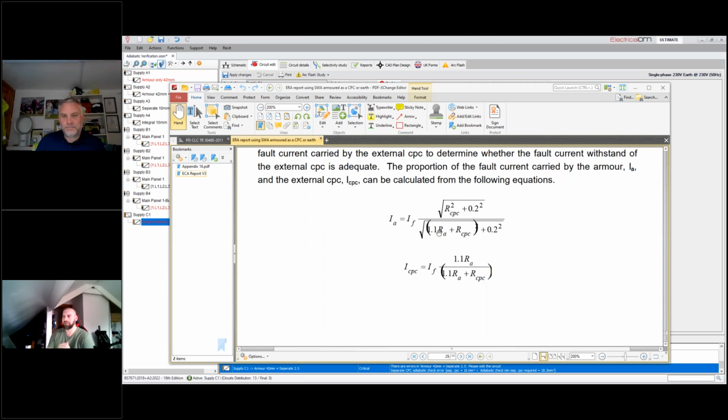Generally, it will be bonded at one end or somewhere naturally for your touch voltages and the like. Generally, it's always bonded for EMC purposes, for the technical report and for the ERA study. Again, these are technical studies. And bear in mind, it is more about when we're using these steels as protective conductors. That's the defining characteristic: if your steel's being used as a protective conductor and you're running it with other conductors that are copper in relation to that protective conductor.